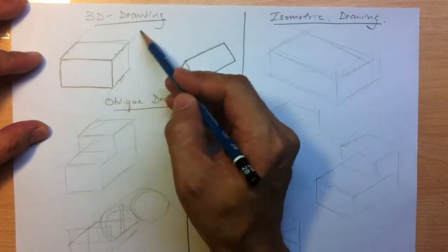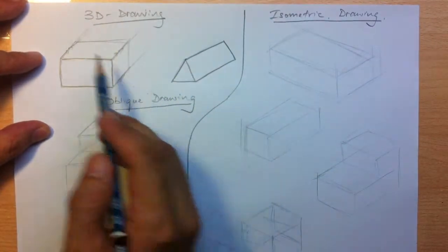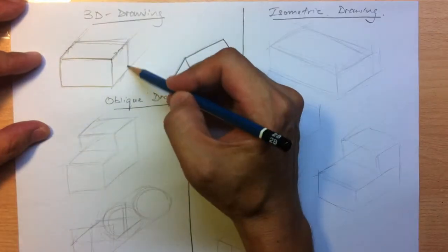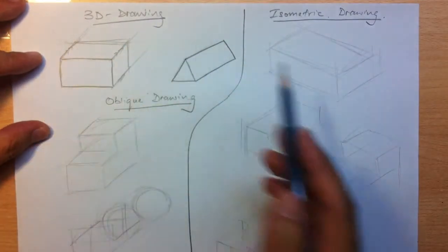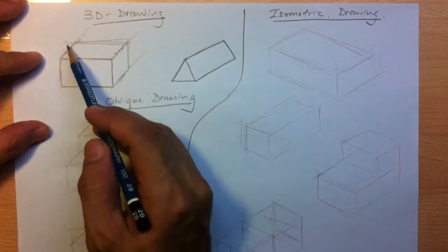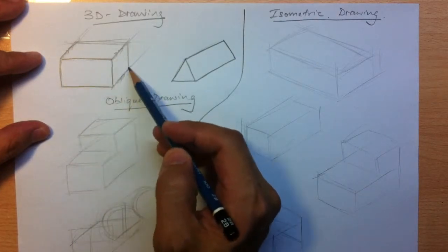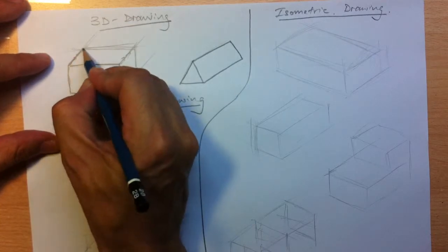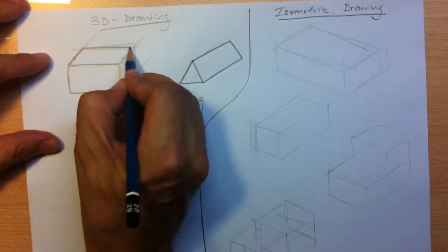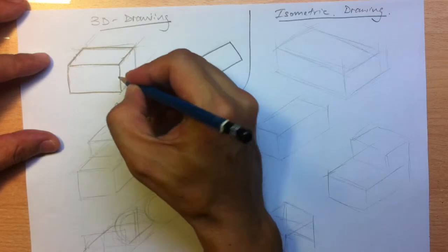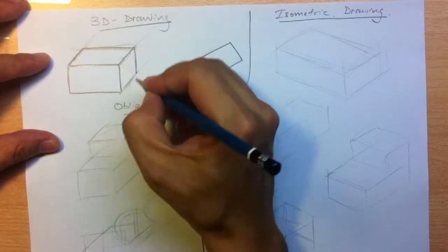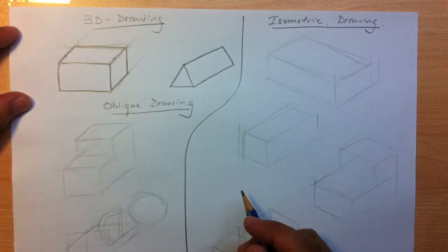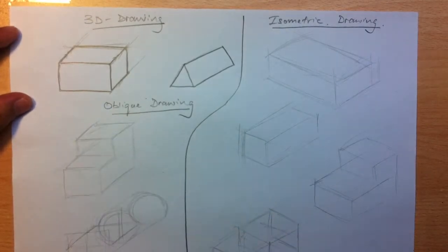And you just slant in the same angle, and then you mark off the depth of the object with a line, same distance throughout along this slanting line. Now when you are done with it, you simply darken it to the correct outline that you want, and there's your first drawing in oblique for a rectangular block.